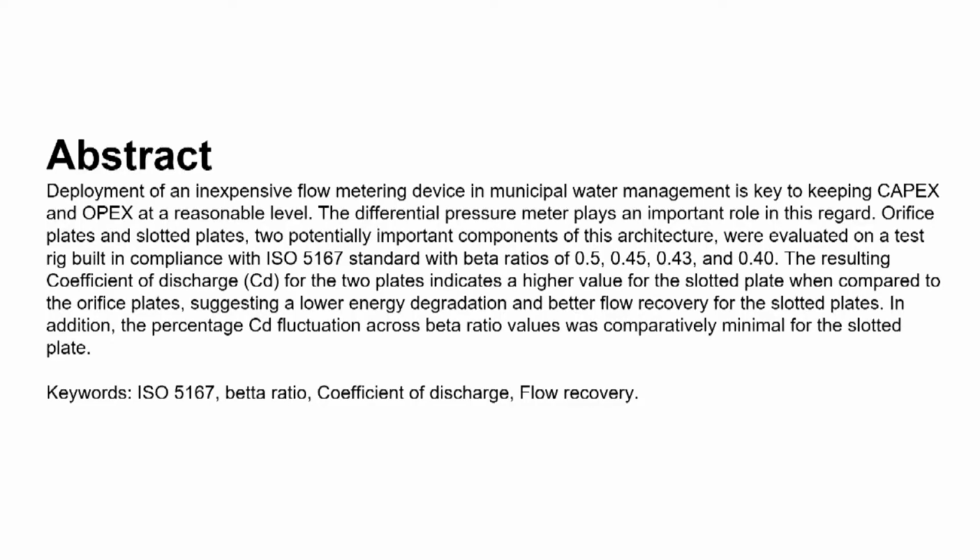Orifice plates and slotted plates, two potentially important components of this architecture, were evaluated on a test rig built in compliance with ISO standard 5167 with beta ratios of 0.5, 0.45, 0.43, 0.40. The resulting coefficient of discharge for the two plates indicates a higher value for the slotted plates when compared to the orifice plates, suggesting a lower energy degradation and better flow recovery for the slotted plate. In addition, the percentage CD fluctuation across beta ratio values was comparatively minimal for the slotted plate.